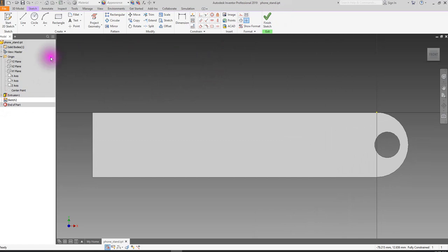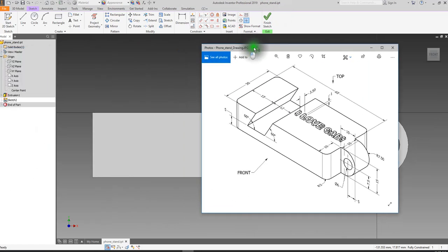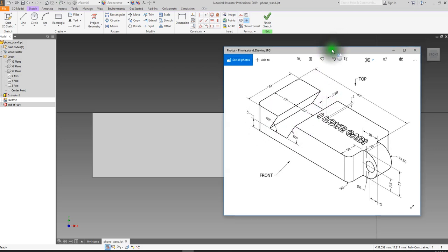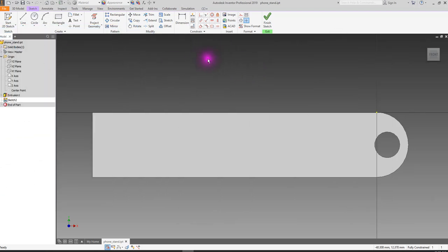So what we want to do now is, let's bring in the drawing. We want to make this cut here. So we will sketch this section, and then we will cut it using the extrude tool, but instead of adding material, we will remove material. So we need 2 lines, or actually 3 lines, plus the top, 4 lines altogether, and they need to be at a specific angle and some specific dimensions. But let's worry about the dimensions in a little bit. Let's start again by making a rough sketch.